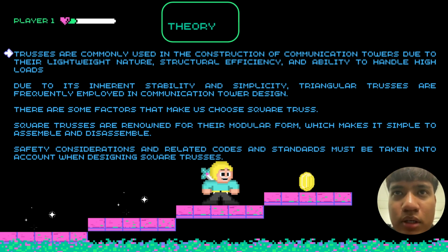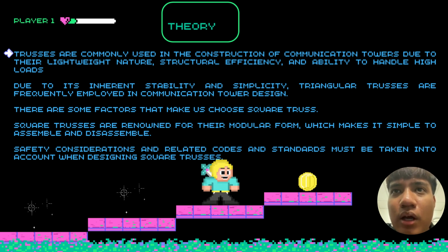First of all is the design and the construction. For our truss, we use a square truss. Square trusses are commonly built out of joined aluminium or steel tubes. In order to provide strength and stability, the member cross-sections are often round or square. The truss pieces can be connected together to form greater spans or unique configurations. They are frequently made in a standard length.